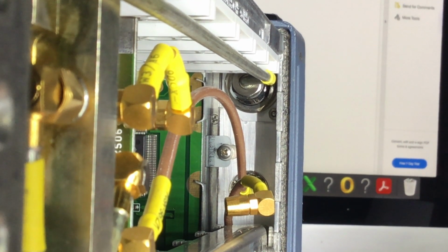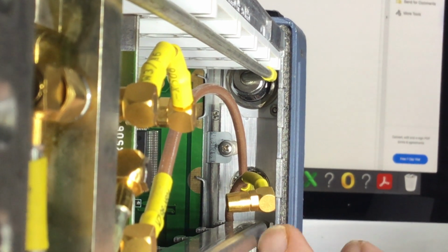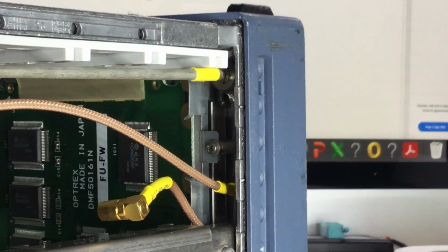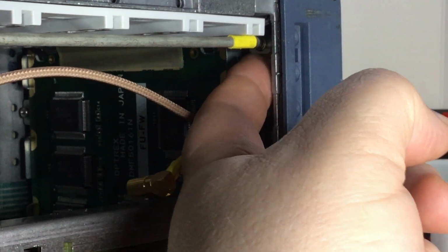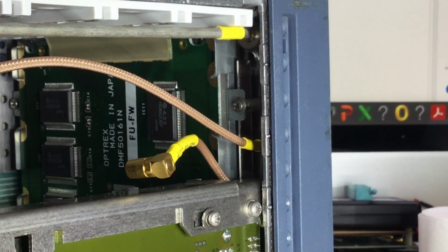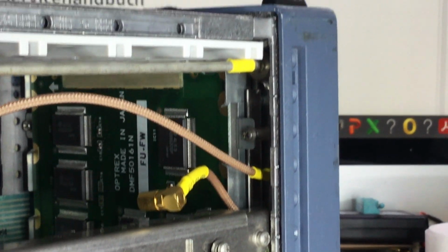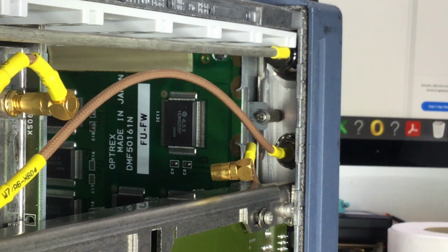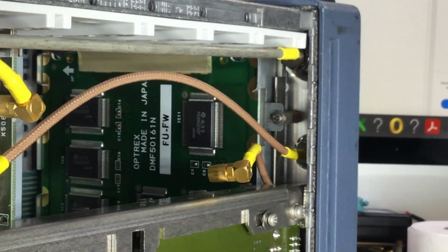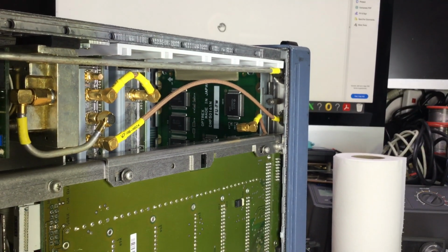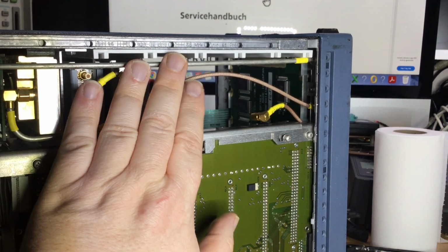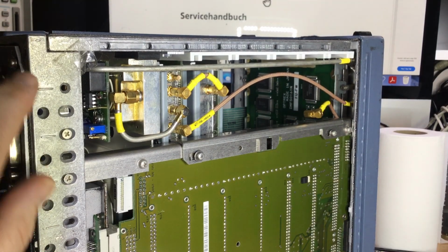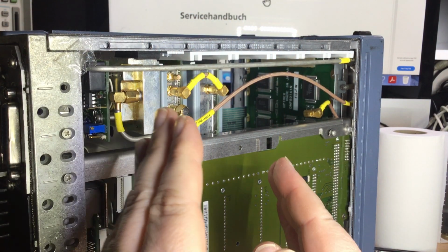when the front's removed. I can't get onto this because when you look at the depth, trying to get something into here to turn, there's just no turning space. Technically a pair of long nose pliers might be able to do it, but it depends how tight that nut's on, and it's going to chafe it up and make it look quite bad. So I think the easiest thing to do, because the front won't come off unless you remove this, is to probably disconnect the cable up there, pull the cable out, bend it out so that the front then can be